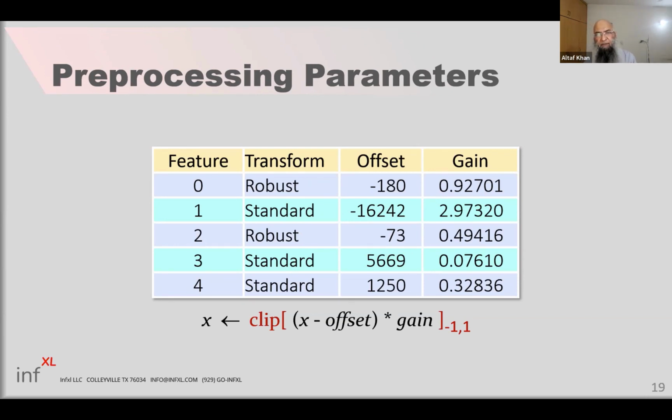Or sometimes something else is happening. For example, these days, when you buy accelerometers, many times they are 10-bit accelerometers, so the output is already digital. If you have 10 bits, all that you need to do is ignore the 2 lowest bits, or in some cases the 2 higher bits, and connect it directly to the inputs of the network. So in that case, really, you're not doing any practical pre-processing.